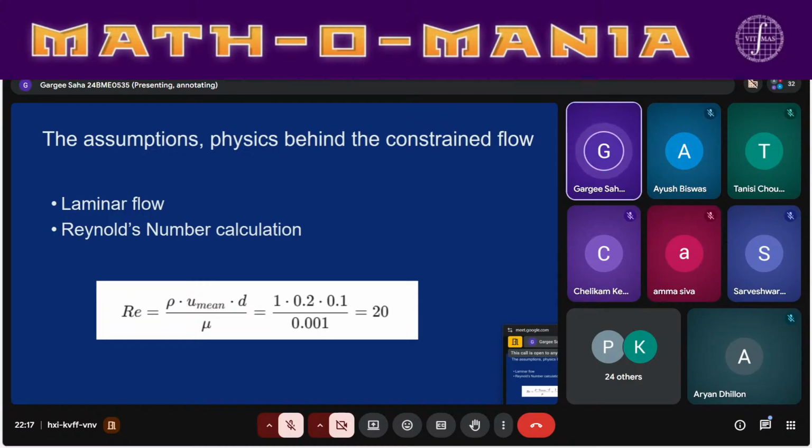So we will visualize the laminar flow as made out of layers of molecules, one on top of the other, such that there is relatively low movement between these two layers as they hold on to each other. Laminar flow will also cause the inlet flow of the fluid into the rectangular chamber to be parabolic, which we will cover in a little while.